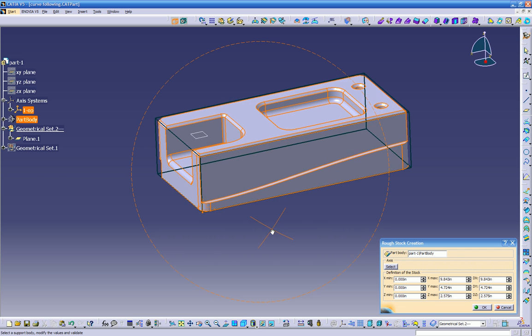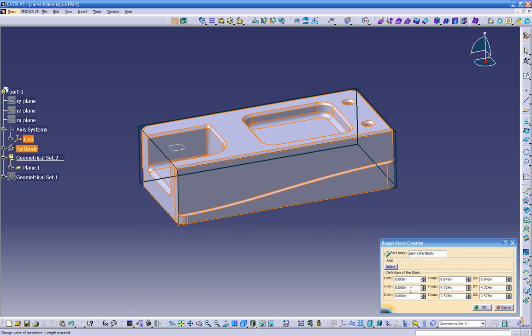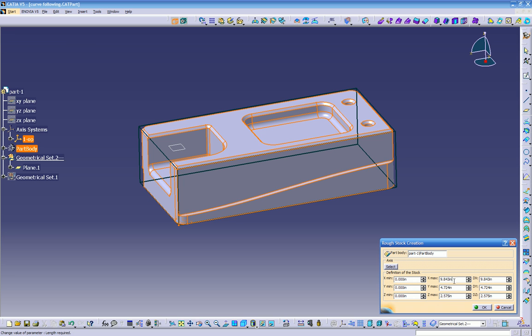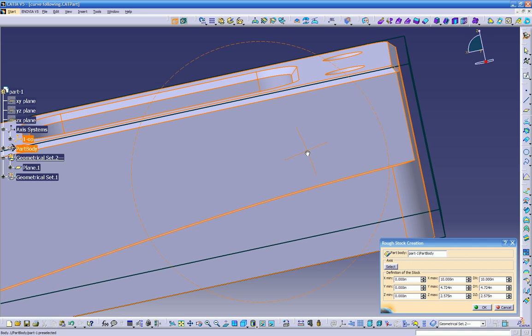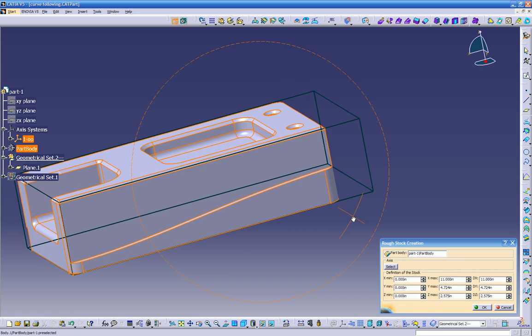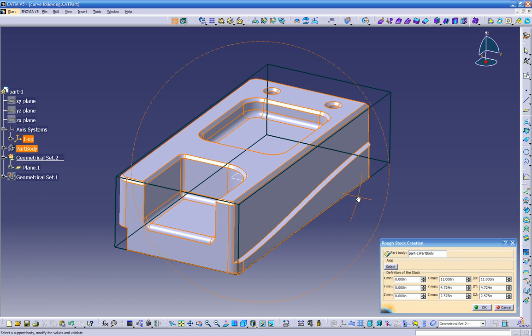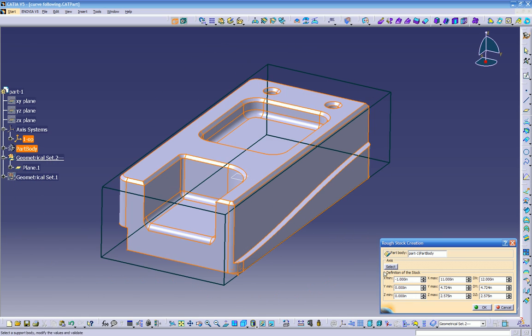But if the stock is bigger in real life, you can come back in here and change it. See, right now it's 9 inches. For example, if your stock is 10 inches, you just click 10 and see, it automatically increases your stock. See the difference right here? It's making it bigger, so you can see you have a couple options you can choose from, and also over here.